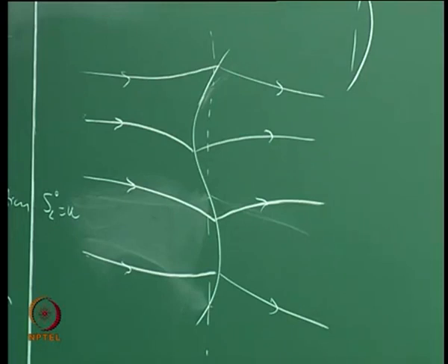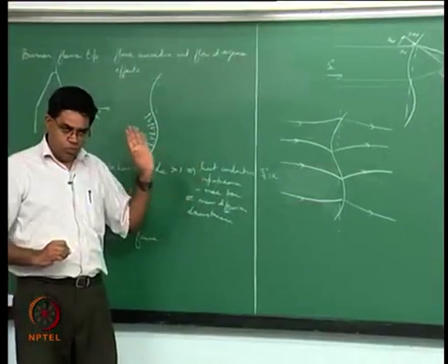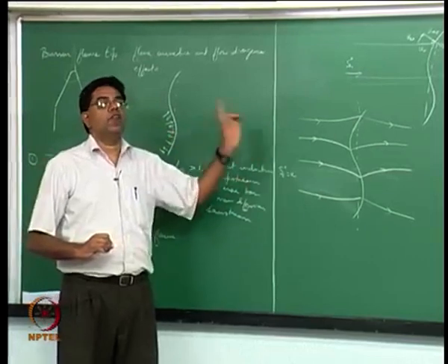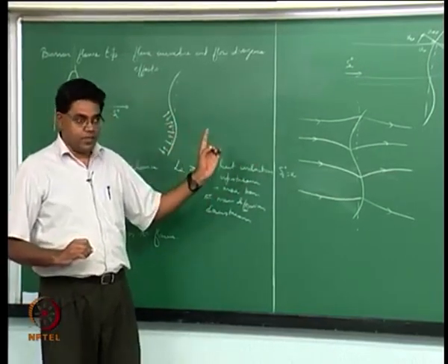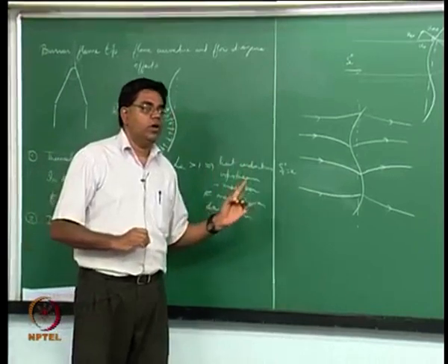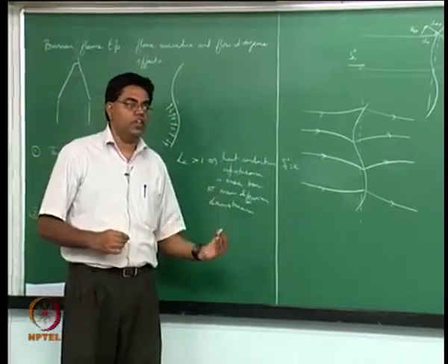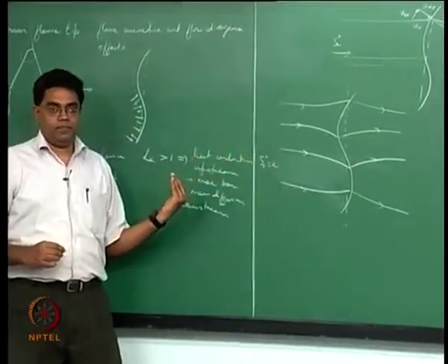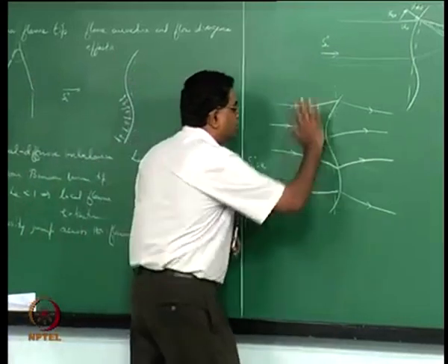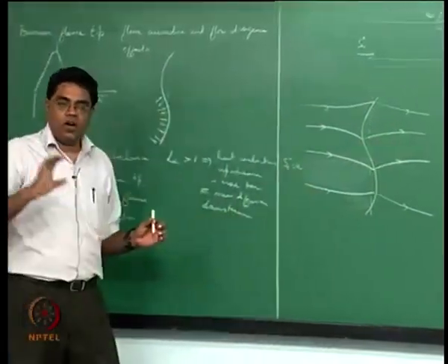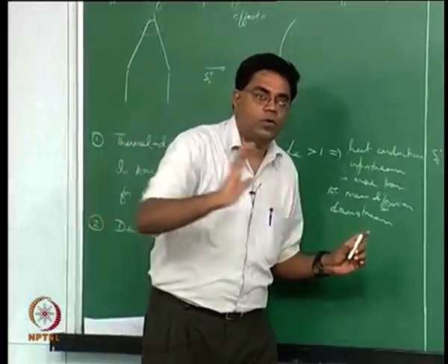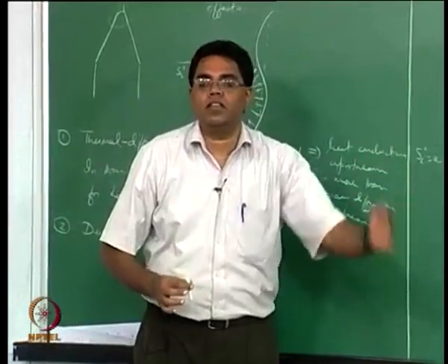That means, and this is very important, I think I mentioned this earlier, the way we always want to think about flames, and I will reiterate this when we are dealing with triple flames after doing diffusion flames, is that flame propagation speed is always relative to the flow speed far upstream of the flame. That means you don't want to worry about all this mess. It all boils down to how much I have to open the valves for my flow to set in so that the flame is approximately stabilized.